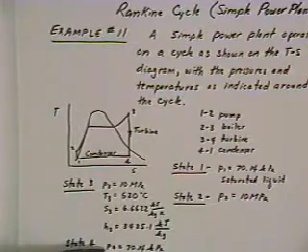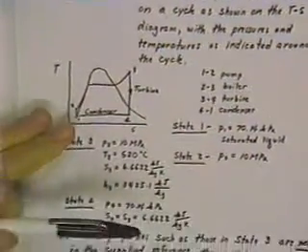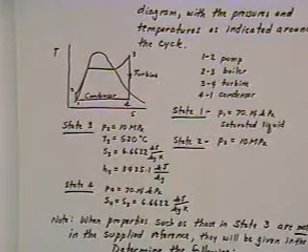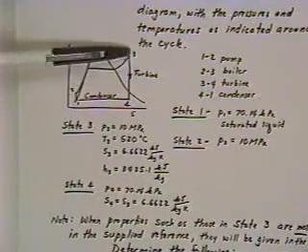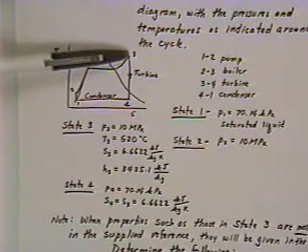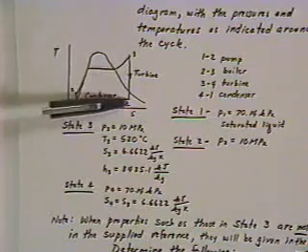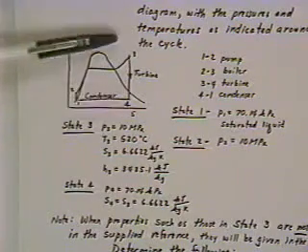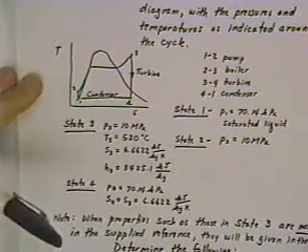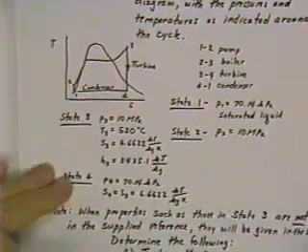And state 4, we're given the pressure conditions here and entropy conditions. And we're given that in our very simple cycle, highly idealized, the turbine work from 3 down to 4 is reversible, so that the entropy is constant from state 3 to state 4. So this is an isentropic expansion through the turbine.